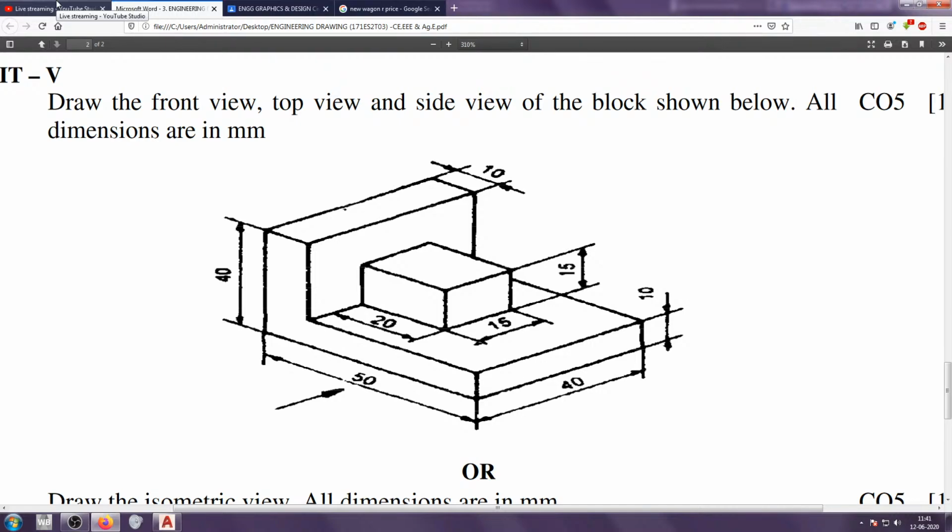We are actually taking the left side view most of the times, right? But here, if you take the left side view, that is also fine. But if you take the right side view, like you're watching this object from this particular direction, then you will be able to see this face and this face. So try to avoid these hidden edges. If you watch this one from this side, that is also fine. He just mentioned the side view, but what he is actually trying to say is draw the side view of this one, which is nothing but the right side view.